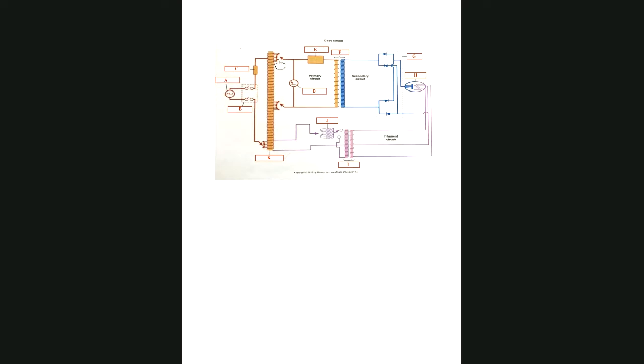So here's our taps for major and minor kVp. And this meter here, what meter is this one? The kVp meter? That is correct. You just have to know what the meters are by where they're located in your circuitry. Remember, I told you they just show you that with the arrow in it. That represents a meter. So it could have been here, it could have been over here. If it was over here, it would have been what meter? mA. Correct.